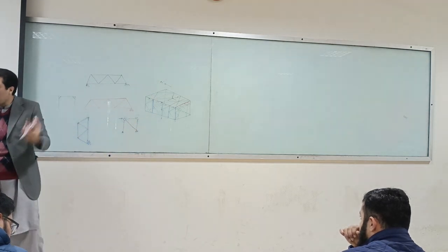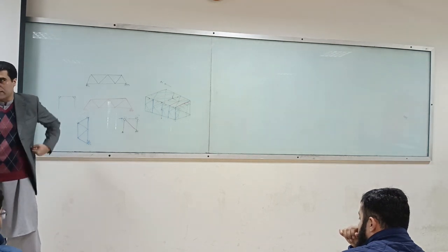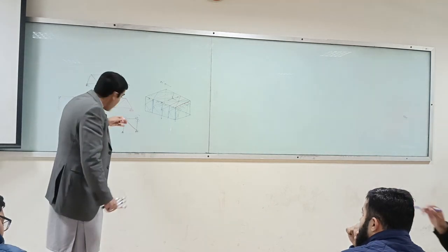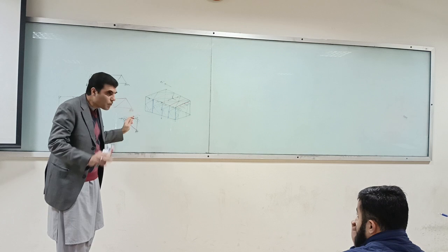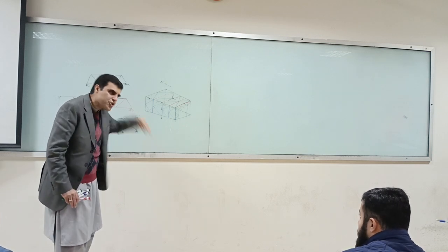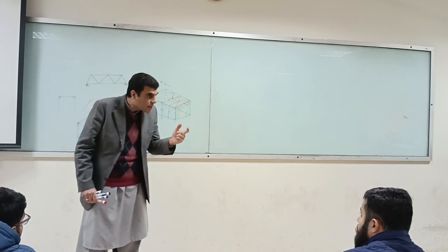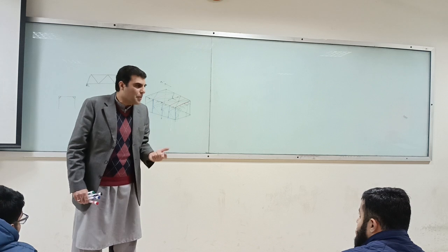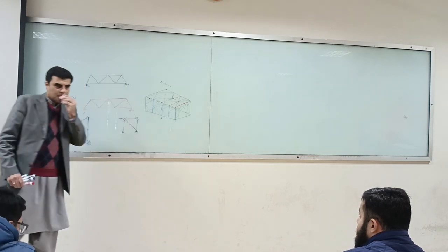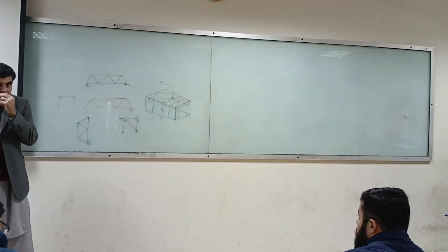Okay? So that's how you provide your bracing in order to stabilize the whole structure. Any question? Is the bracing also pinned? Pinned, everything pinned, no fixed connection. Everything is pinned. Just through triangulation you are trying to bring the load down. If you provide it fixed, then it will generate moments, and you don't want moments in your trusses. So everything is pinned. Any question? Okay, is it okay?